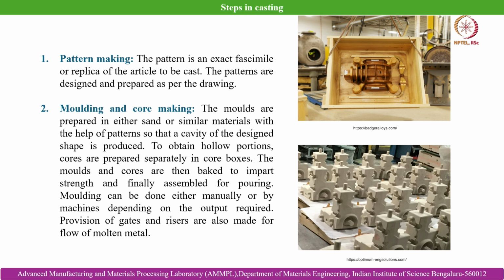If we talk about sand casting, the pattern is needed, and then we need to ram the sand at the periphery so that we can get the desired mold. That mold has to have sufficient strength and structural integrity so that it can withstand the metallostatic forces exerted by the liquid melt when it is filled within the mold cavity for subsequent solidification. These are the attributes that are necessary.